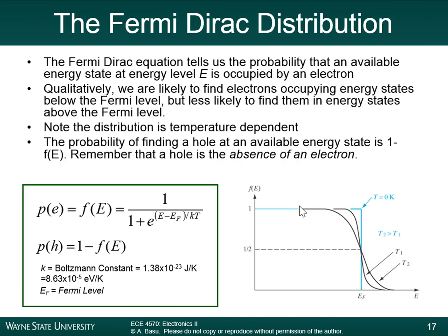All right. Now, the Fermi function also shows another important thing: it's not black and white, meaning it's not a completely sharp drop-off. What I'm trying to say is that a completely sharp drop-off would mean that below the Fermi level, all the states are full, and above the Fermi level, all the states are empty. Okay, that's not the case. That only happens if you're at 0 Kelvin.